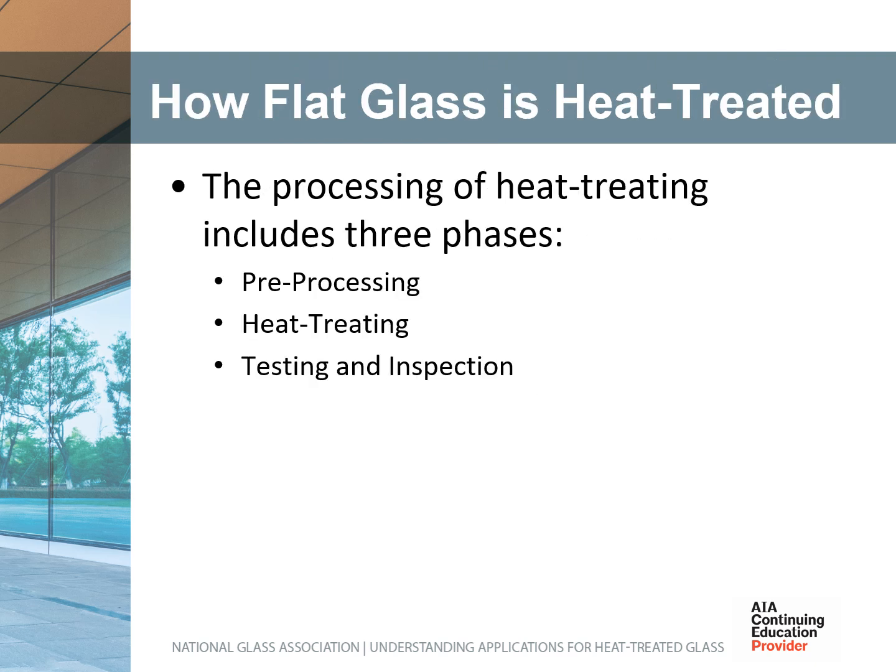The most commonly used process for heat treating architectural products calls for glass to be cut to the desired size, transported through a furnace, and uniformly heated, then rapidly cooled by blowing air uniformly onto both surfaces simultaneously.